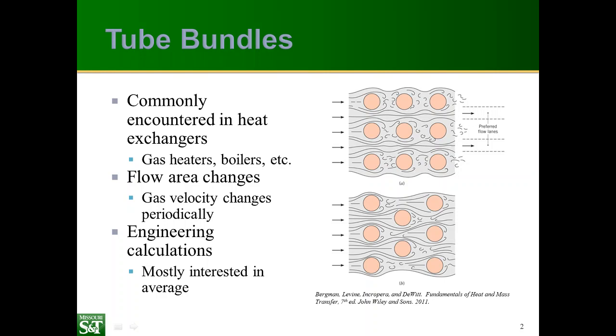the geometry here with the tube diameter, which is the distance across one single tube, as well as the tube pitch. Now, in aligned bundles like this one, where you have preferred flow lanes and so on, you have both a vertical pitch, which is the center to center distance, and you have a horizontal or longitudinal pitch, again, center to center distance. The issue with these is that the preferential flow path usually leads to degraded performance because the fluid doesn't mix very well.